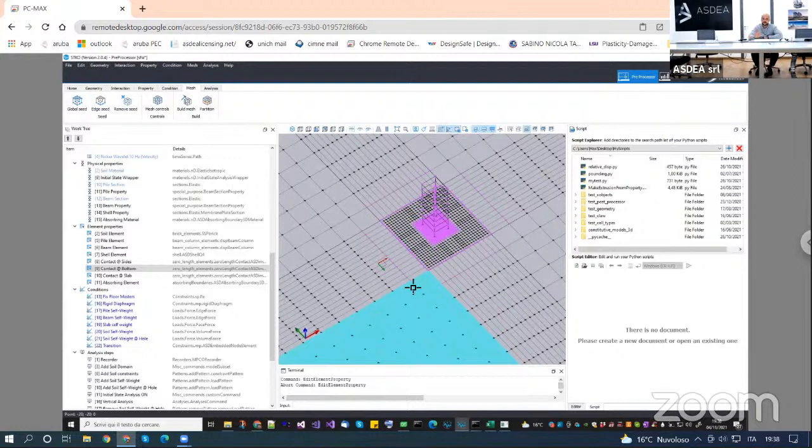The only problem is that it's not going to be so easy, because it's not easy to find what the nonlinear G modulus of a material is. For example, if you use a plastic model and you get the shear modulus from the tangent matrix, sometimes it can be near 0. If you have softening, it can also be negative. But then when you unload, it will suddenly become the elastic G modulus. So it doesn't make any sense in that case because you will have very high oscillation. So what is the G modulus of a nonlinear soil?